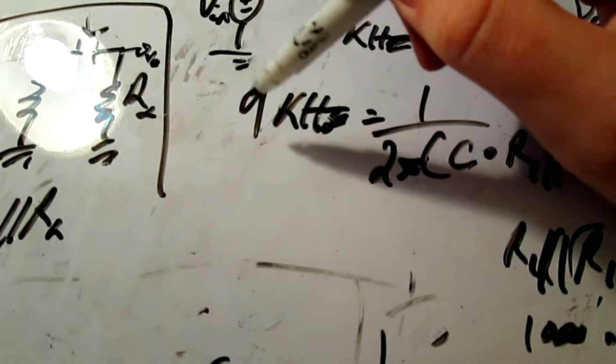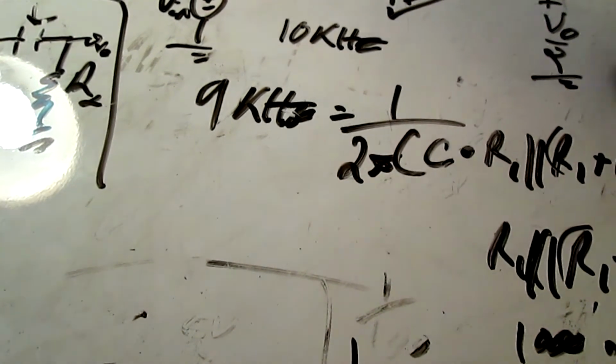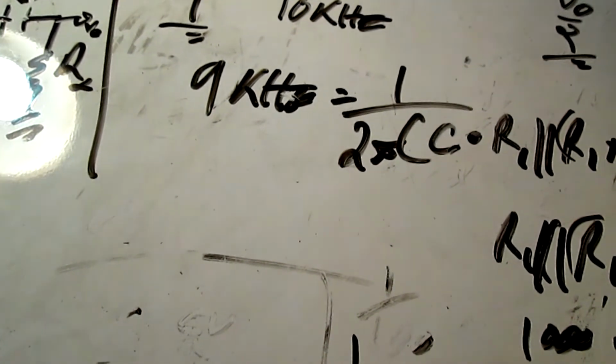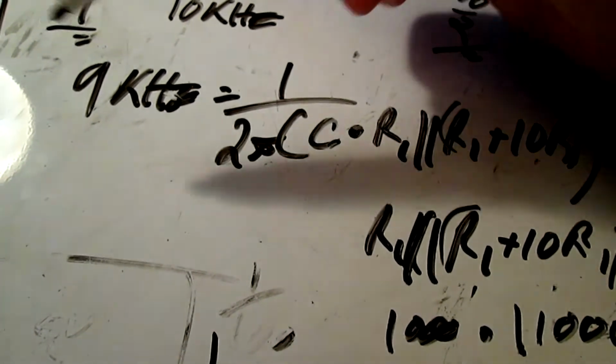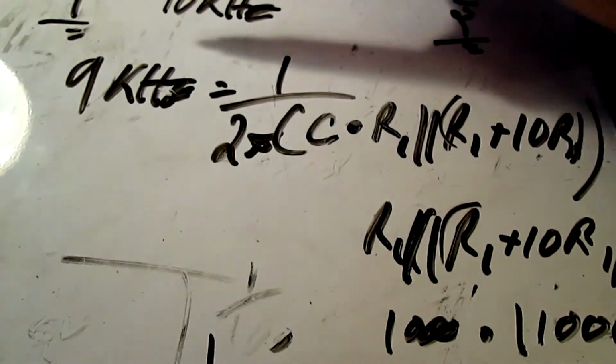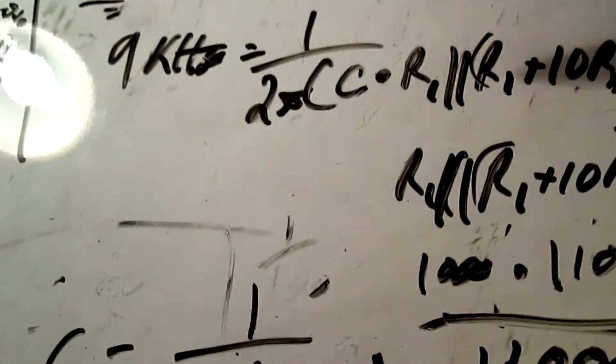I worked with a 9 kilohertz. I don't care, I'll let through everything past 9 kilohertz. Because my signal that I'm transmitting is 10 kilohertz. I want to make sure not to cut through that. And nothing's ideal, so you always want to give yourself space for error.